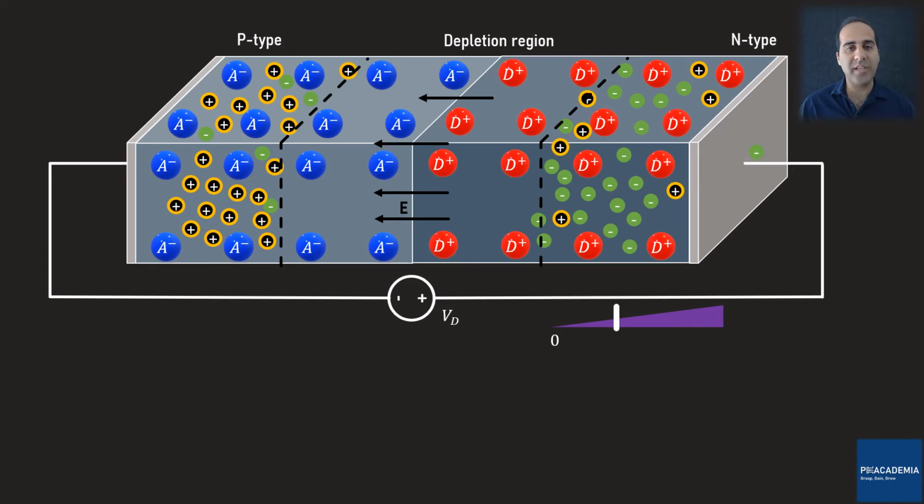a free electron leaves the device on the other end through the positive metallic contact. On the N side, the minority charge carriers are holes and, similar to free electrons, they wander around. When a hole is within the diffusion length Ln, it is affected by the depletion region electric field and is sucked into the P semiconductor. Now the P semiconductor has one more hole in its neutral region.